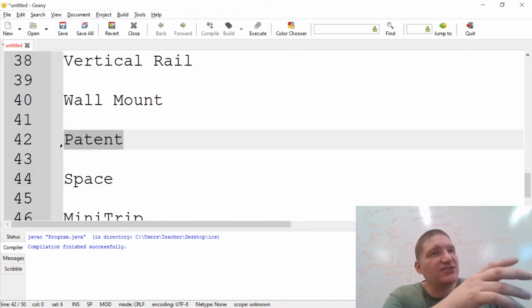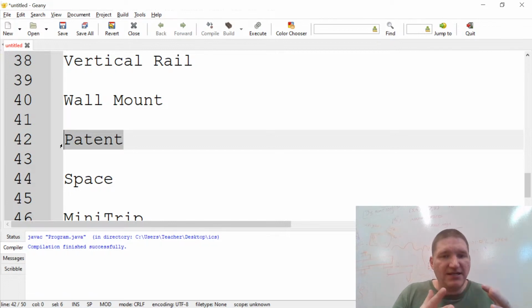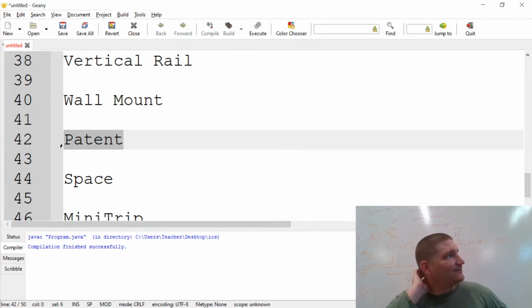The reason we think it skirts the patent is that the Tripteron patent says that each of the axes are decoupled from each other and they're uniform in the way they enter. In this case, I have asymmetric ways I tilt each of the carriages to accomplish what I want. So I don't get a nice decoupling, and I make my life a little harder on the firmware side, just slightly. So I think I don't infringe on the patent.